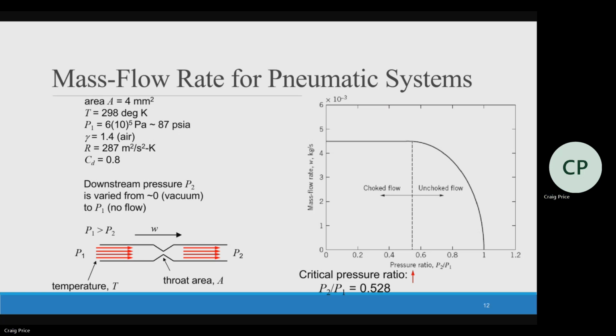So, for example, let's say we were able to hook up your water bottle to one of these right here. We're going to take someone's water bottle, maybe a metal one that could probably hold up pretty well. We hook it up here and get the flow rate going. First, there's going to be a large pressure difference, because I'm going from the compressed air into the water bottle, which has just atmospheric pressure.